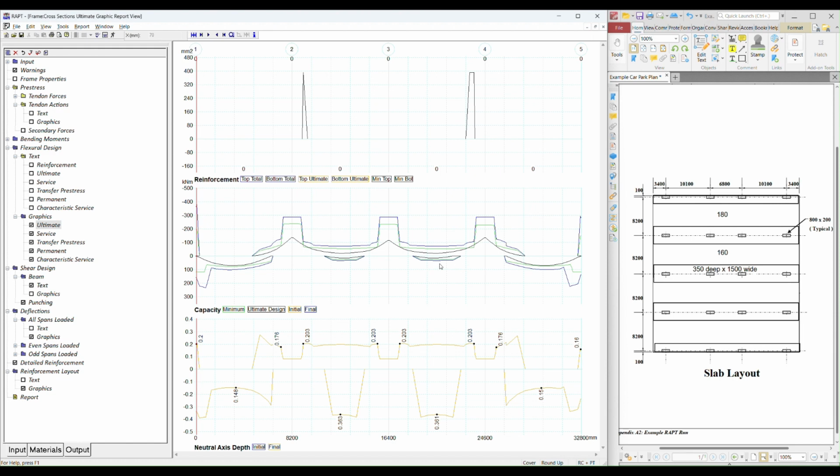So you would either increase the depth of the section to make that 190 and 170, and then you could look at reducing the pre-stress, or leave it as is, as long as you don't have too much restraint in the system, which would be fine in what we're showing here, because we really don't have much stiffness in these columns in the weak bending direction.